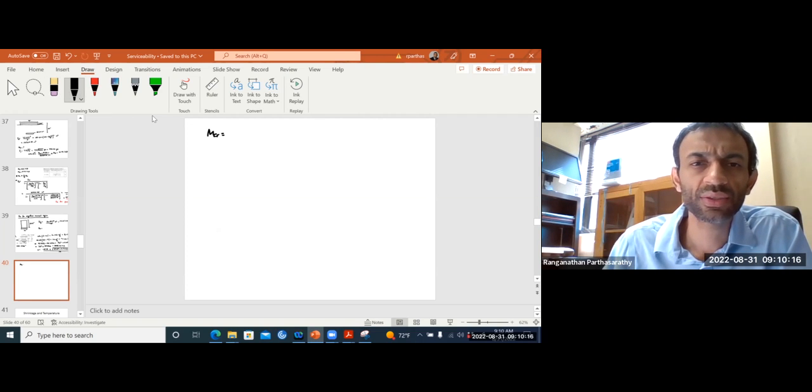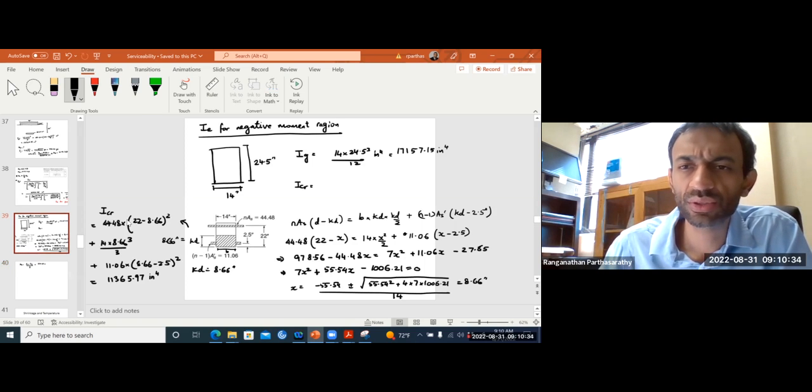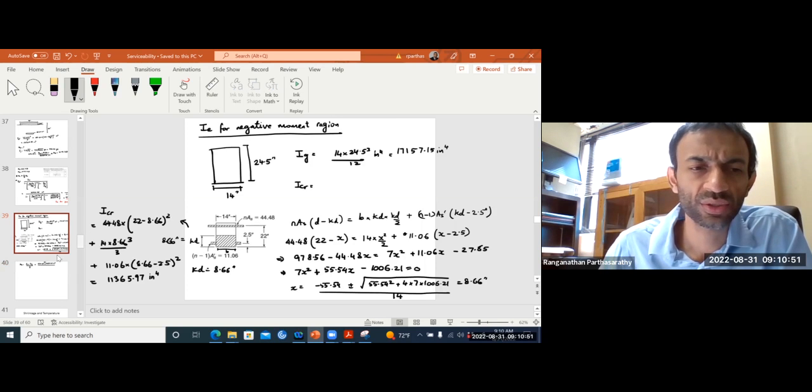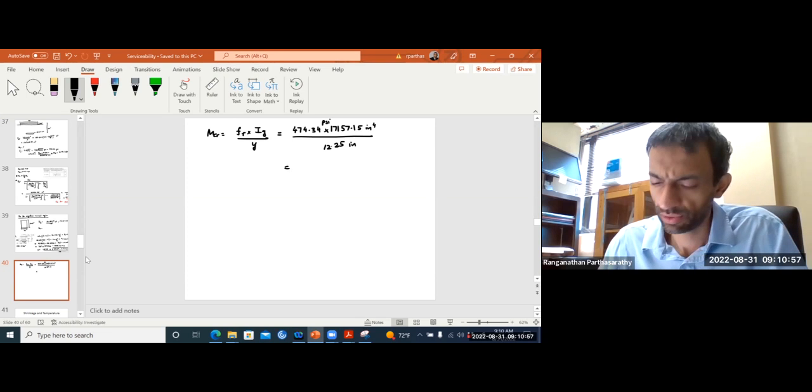So MCR is FR times I gross divided by Y. FR is 474.34, I gross is 17,157.15, this is psi, divided by Y. Y is just 12.25. So what do you have?